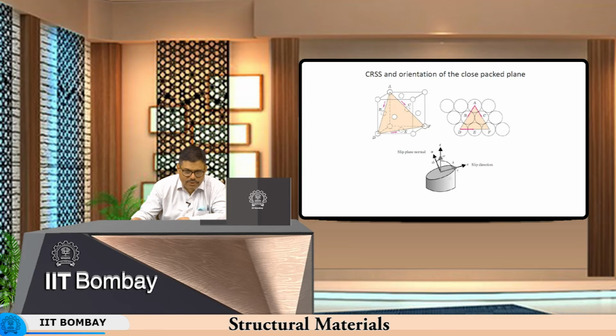And so if you have the cube oriented such that the corner is resting on the surface here, then this plane will automatically come parallel with this 45 degrees direction. So this is some sort of textural manipulation by which you will be able to orient this plane in this direction, and that is why you get different grades of material in the market.